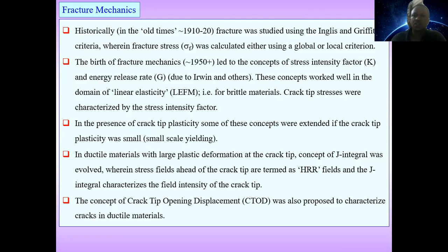This concept worked well in the domain of linear fracture mechanics, or linear elastic fracture mechanics, for brittle materials. Crack tip stresses were characterized by the stress intensity factor. In the presence of crack tip plasticity, some of these concepts were extended if the crack tip plasticity was small, or very small scale yielding.